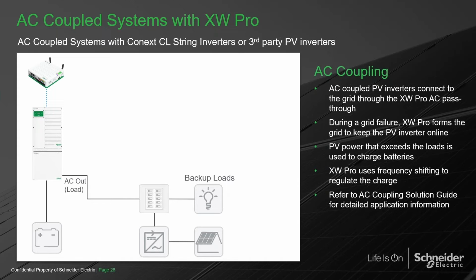But we are actually taking advantage of the frequency going up. The great thing is if you have what we call smart inverters, today's smart inverters actually react by curtailing their power as the frequency starts moving up. So what we do is that we start incrementing the frequency, the slope of the frequency in steps, so that the grid tie inverter starts curtailing this power.